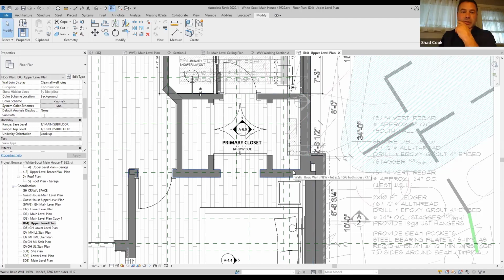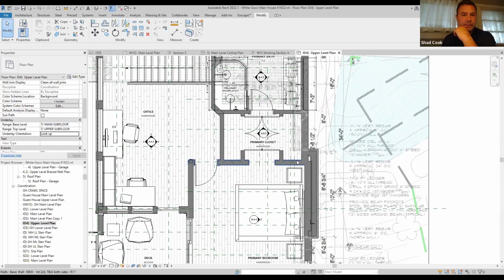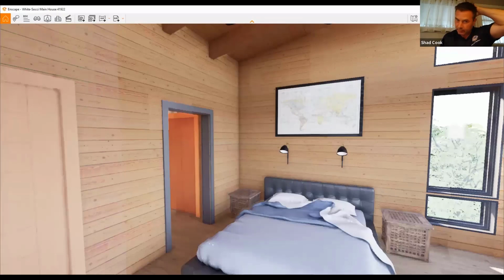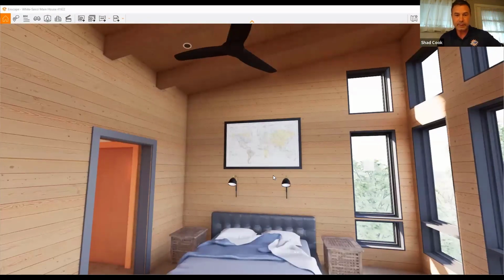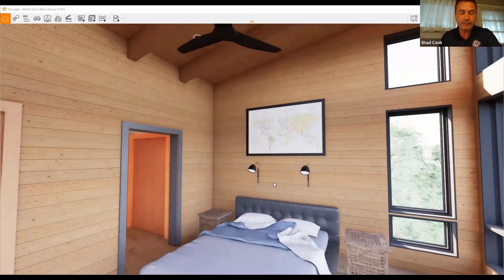I think if we're just trying to hit that bathroom heading in that direction, certainly a 6-inch round duct can satisfy that, or some other similar size of free area to get over to that vanity area. We can do that in the soffit above the bookcase, probably. Maybe even start off a little larger and have one head over through the joist space to catch the other side of the office area on the way.